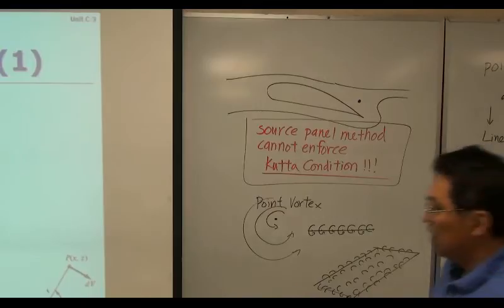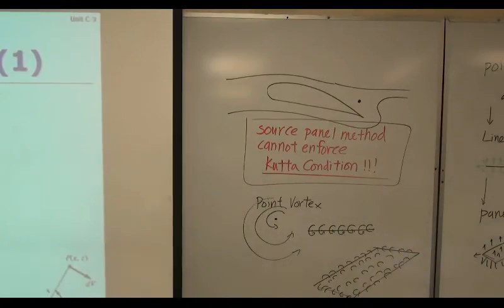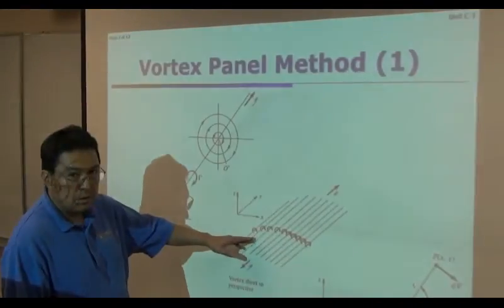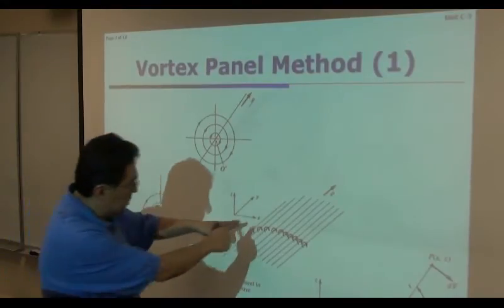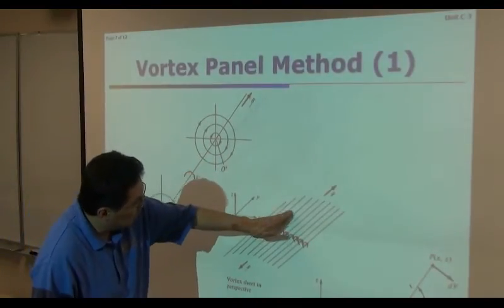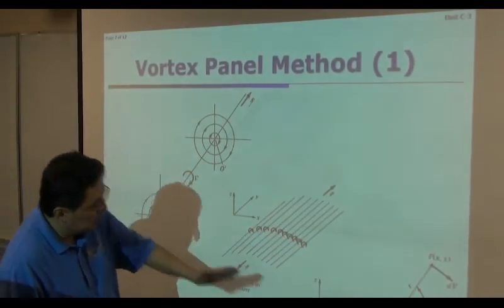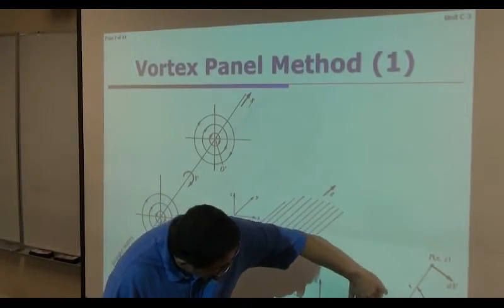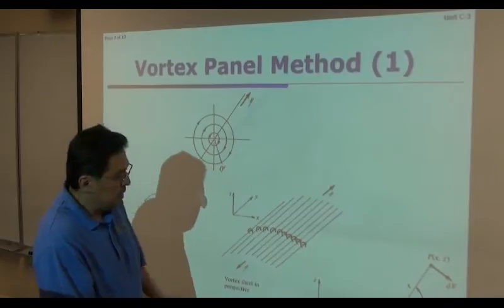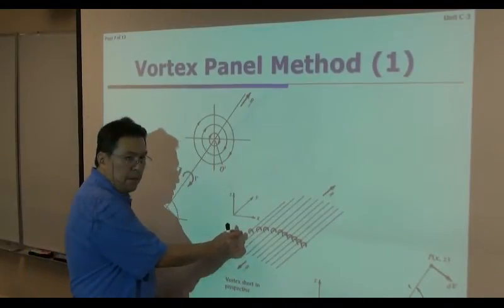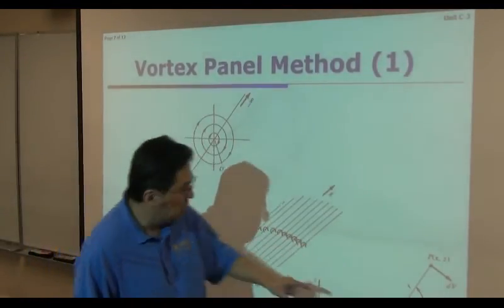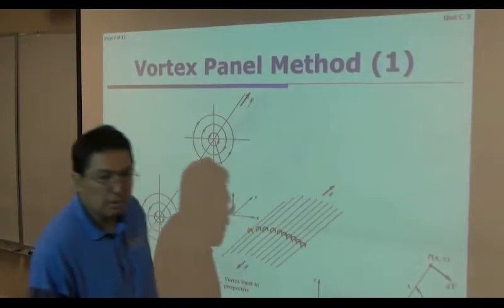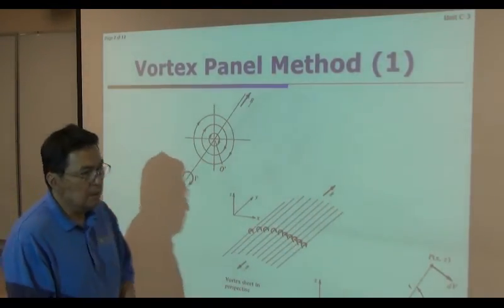Each one of those panels can be used. A small tiny surface of each straight panel is used to represent the curved surface, of course. This is a straight segment for each, but if you use lots of small tiny panels in a series, you can represent a curved surface fairly accurately.